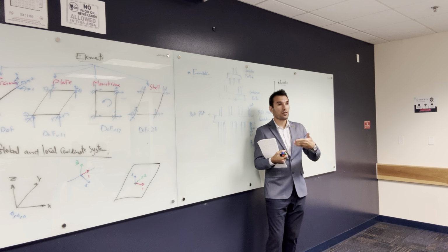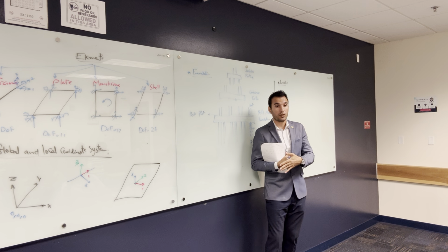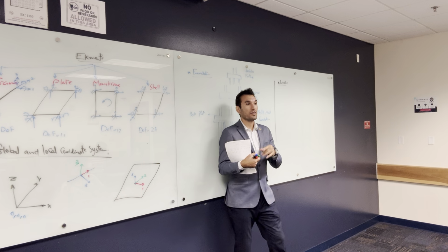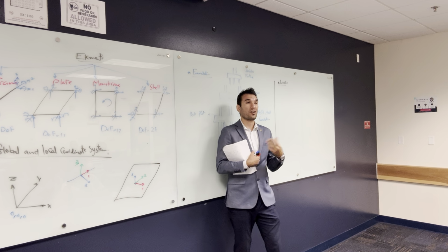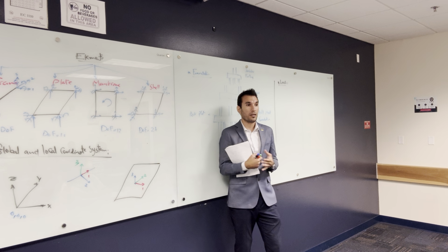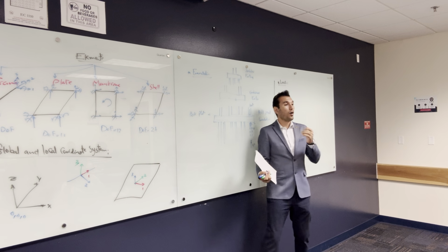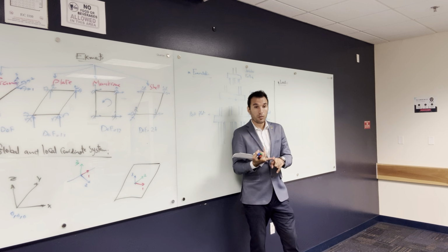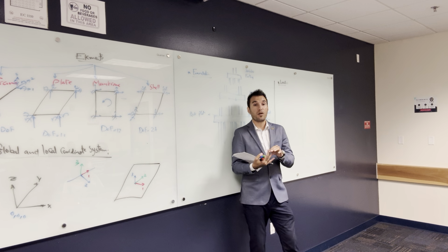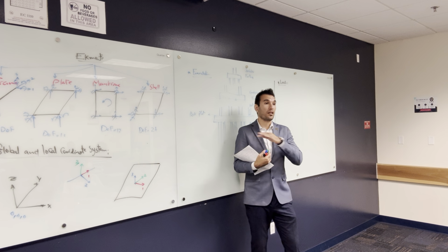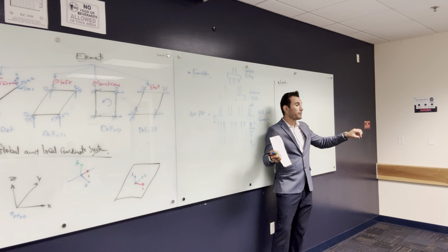And I believe if you look at the ASCE 7-22, whatever version is out there, you are gonna find out that libraries have one of the massive live loads. Definitely also garages have a huge live load. So live load sometimes gets really huge. Also there is a snow load that happens on the roof of buildings. There is a rain load. There is a wind load. There is a seismic load. There are lots of loads. There's special structures that have special types of loads that you have to account for.